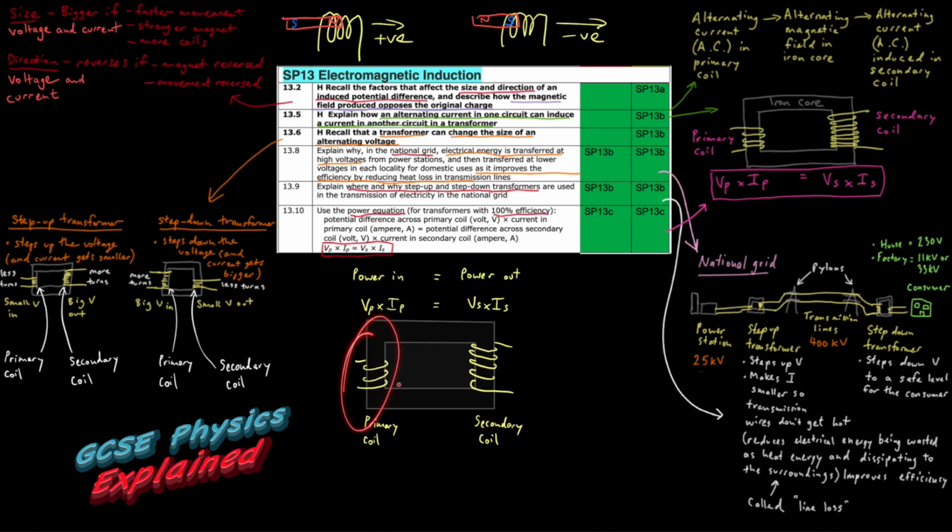And if you put an alternating current in, you can get an alternating current out. Now this transformer, all transformers only work with alternating current. So I've seen them ask a trick question. If they say they put DC in, how much DC voltage will you get out? Well, you won't get any, because transformers only work with AC.